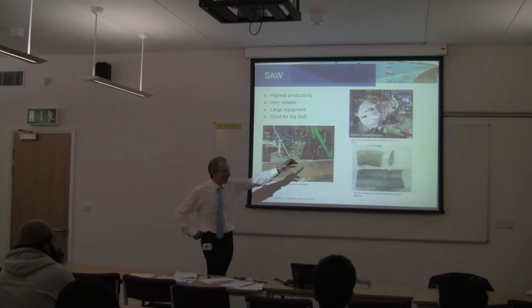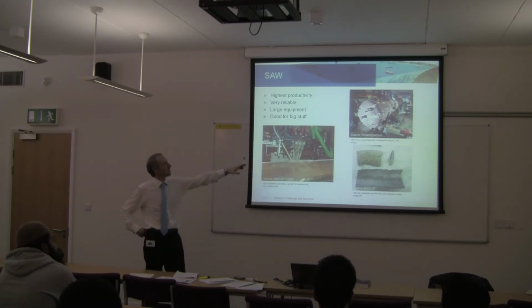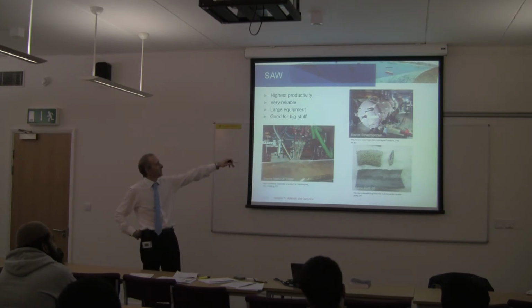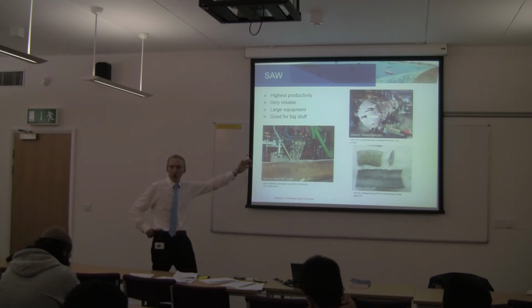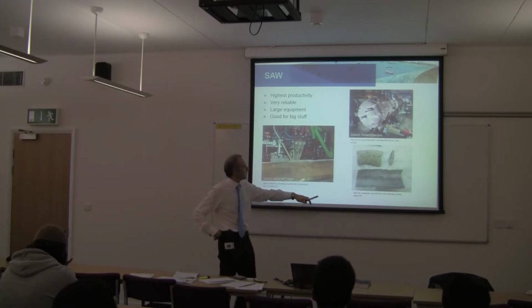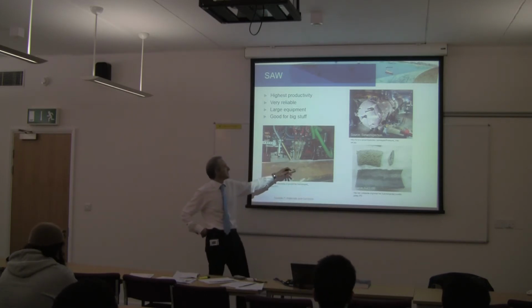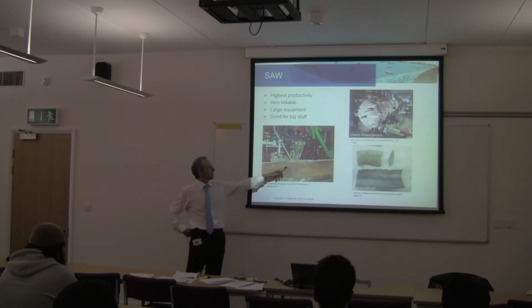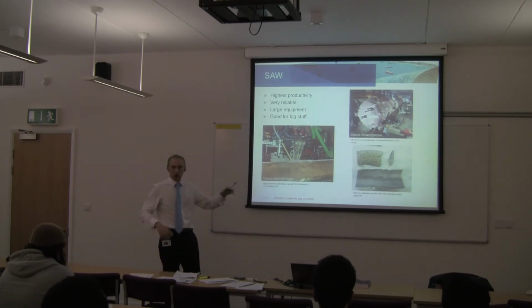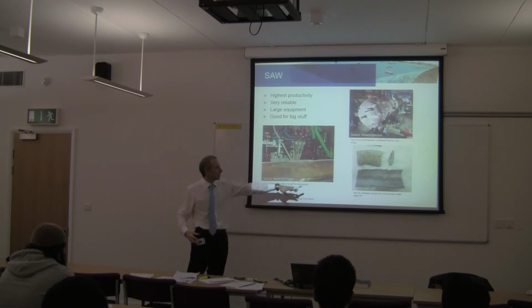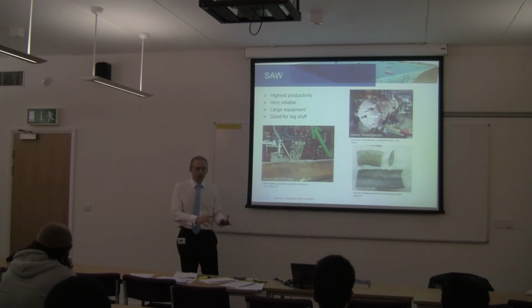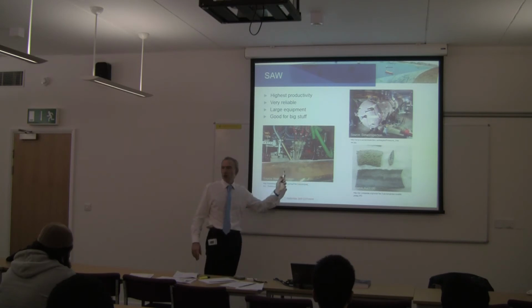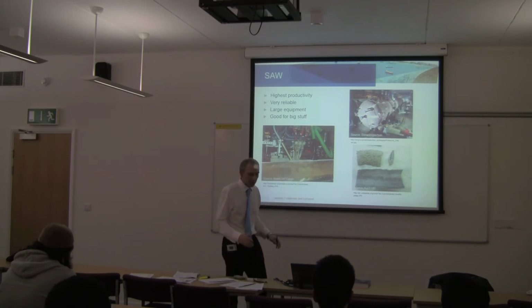The top photo there is a vessel. Again, that gives you some idea of the size of these things. You can see the guy standing there as well. These types of vessels are not only found in refineries, but also on offshore platforms themselves. This here is the powder that you see on top there. When the weld is complete, this powder should just fall off. It looks like an eggshell. That would indicate that the weld is good. If you have problems trying to take this powder off, you know you've probably got a bad weld.